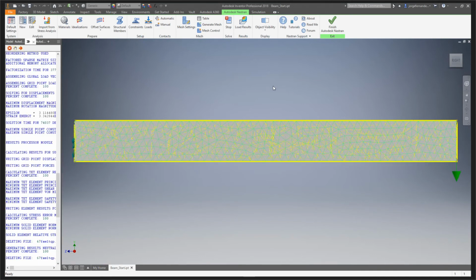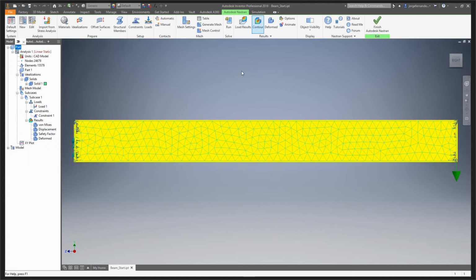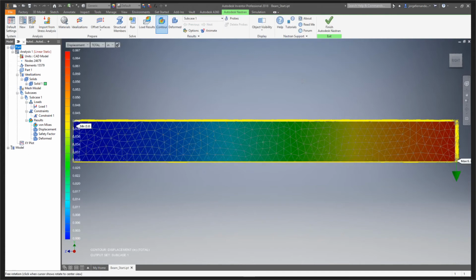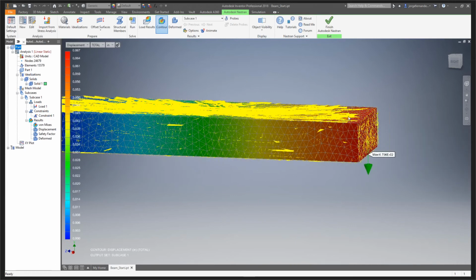Of course, for those of you that are experienced and seeing how these things react, that always helps as well, too, right? Right now, I just changed the mesh setting to a little bit smaller, 0.2 actually. So we're probably gonna get slightly different results, but still pretty close to what we had before. Sure enough, 0.067 is what we're getting now. So as you see here, as I tightened up the mesh, we're gonna get better results in this case.